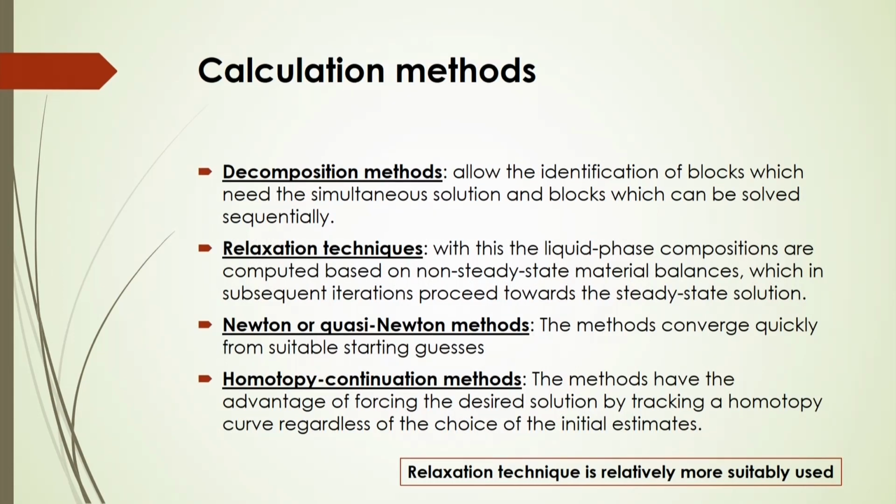Now, there are several methods: decomposition methods, relaxation techniques, Newton or quasi-Newton methods, homotopy continuation methods. Decomposition methods allow the identification of blocks which need simultaneous solution and blocks which can be solved sequentially. In relaxation techniques, liquid phase compositions are computed based on non-steady state material balances, which in subsequent iterations proceed towards the steady state solution.